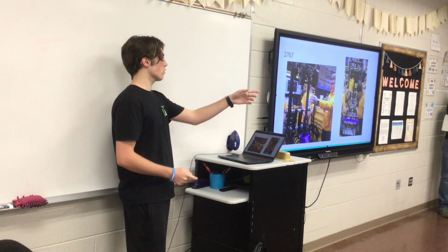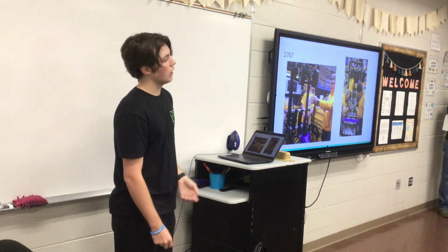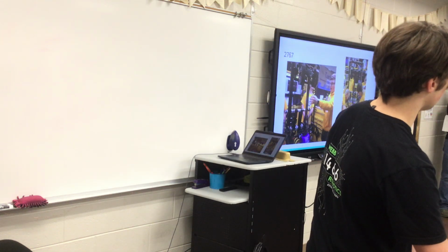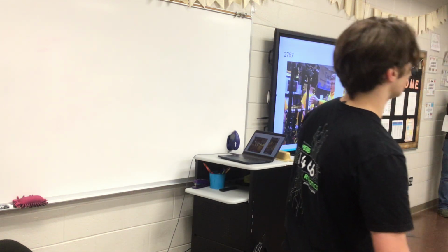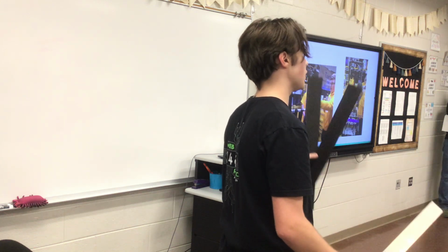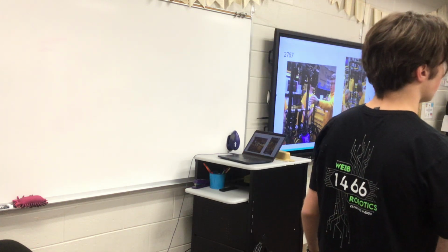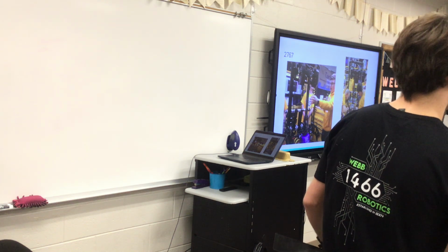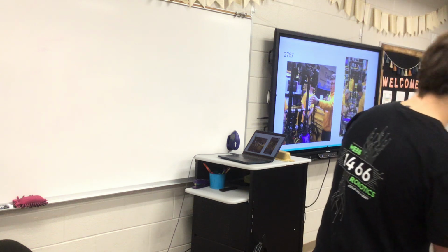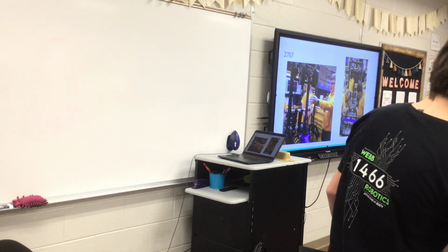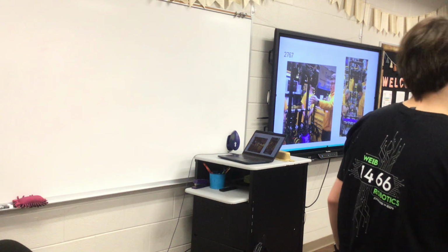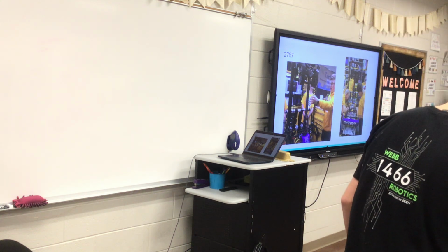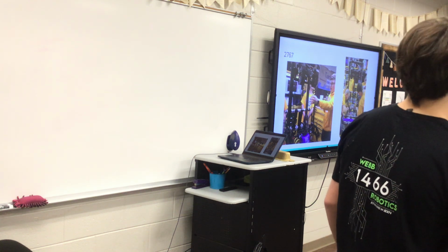To go back to your question about testing, we haven't done any really scientific testing. If you would like to come up here, you can compare the strength to weight versus flexibility of aluminum and these two carbon fiber pieces on this rig we made. You can see the aluminum bends very easily, and it's not as light as these pieces, whereas the unidirectional carbon fiber piece is much stiffer than the aluminum and lighter too. This one is similar to the aluminum in flexibility.